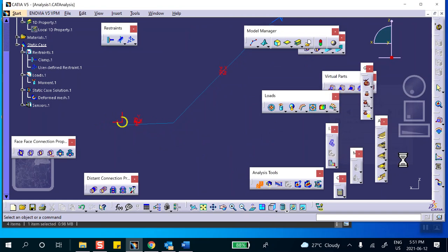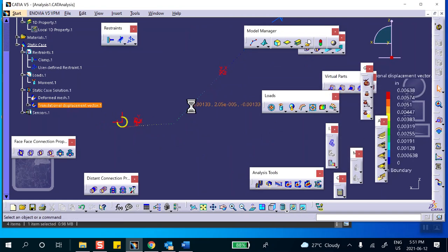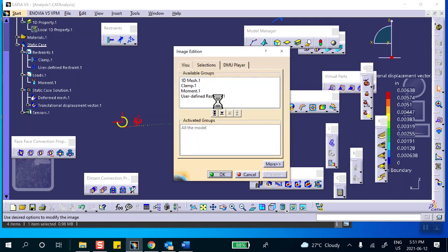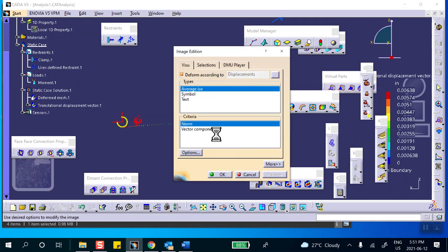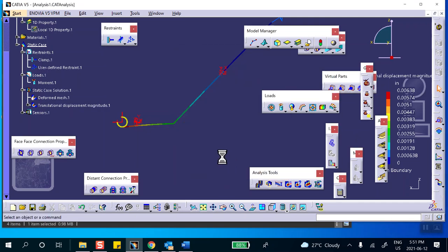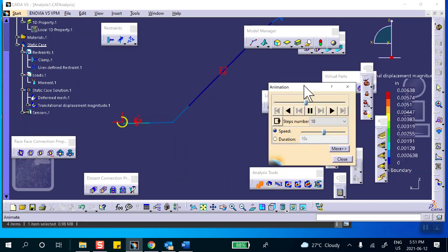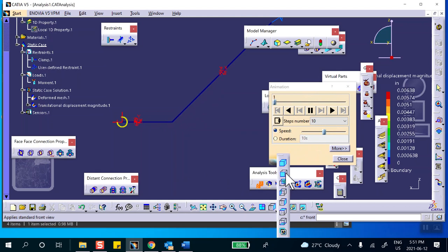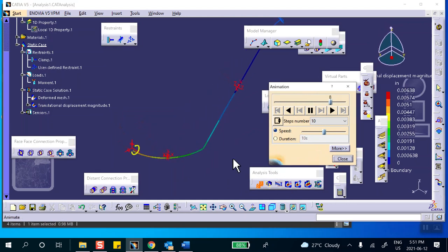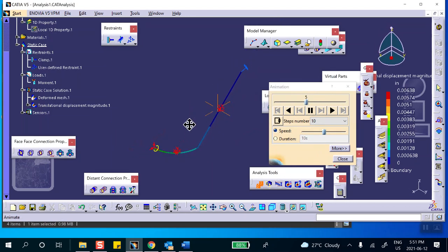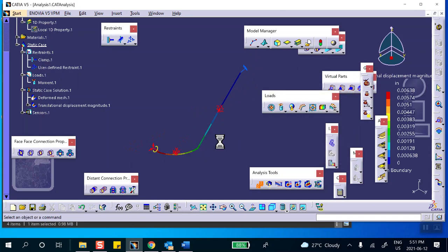You can see that. And if you want to see actual numbers, plot the displacement, double click, and colorful, average ISO, and there we are. So this is the view from the side. The displacements are here, given to you, and you can change the view from some other direction, for example, the isometric view. There we are. Okay, and that wraps up problem 2 for lab section 51.